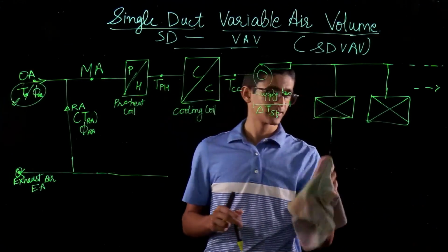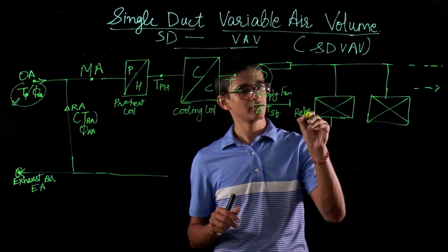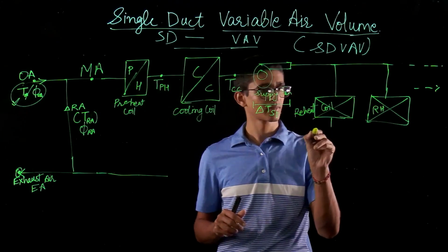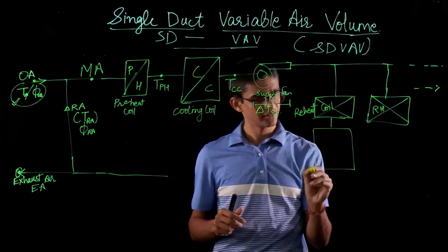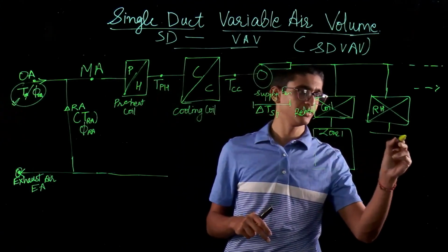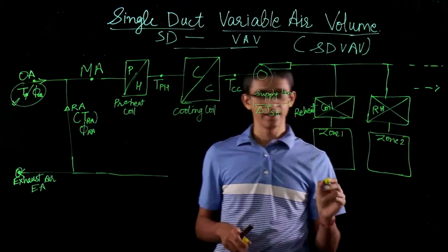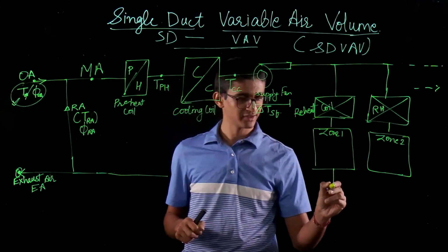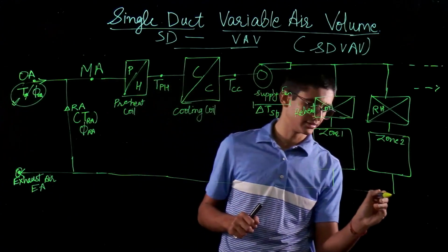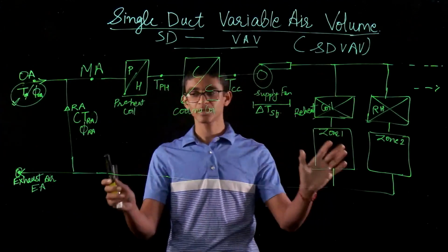So these are reheat coils. This is a reheat coil. Then this could be zone 1 where the air is supplied from the AHU. There could be n number of zones, as I said. This could be the second zone. And after the zone, the air is taken out as return air, that's from the exhaust or vents from my zone. So that's how the common setup is.